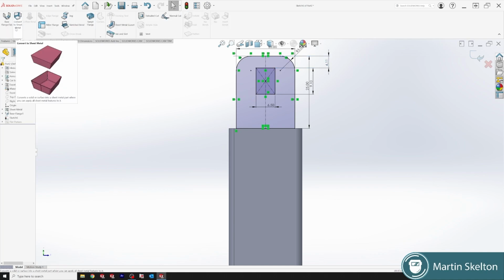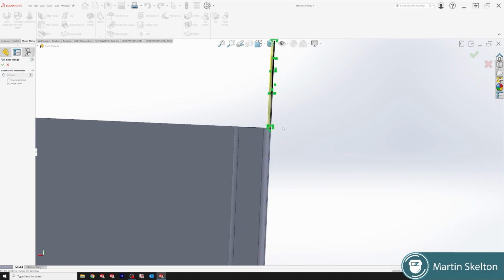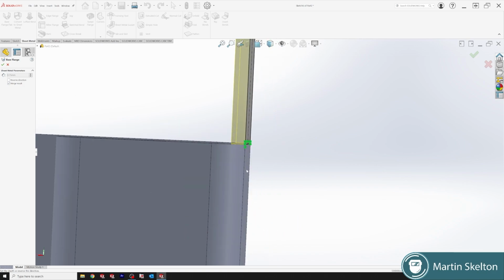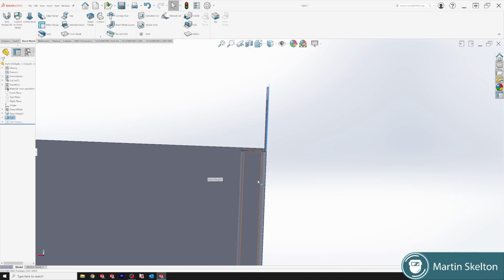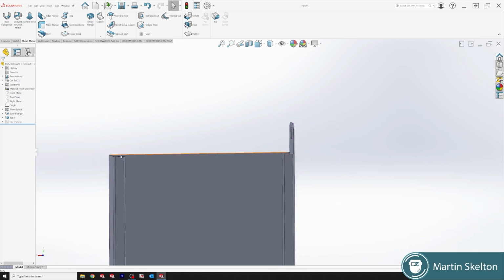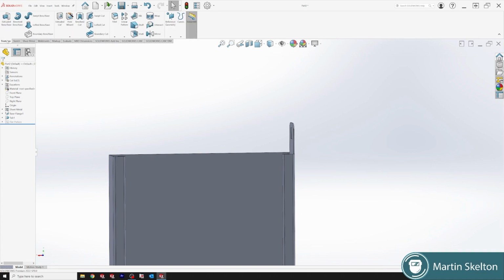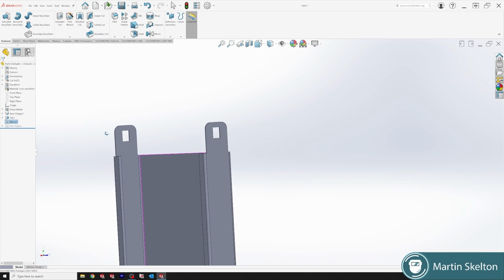Back to our sheet metal. Base flange tab. Merge result. Make sure merge result is ticked. You also check your direction because you might have the reverse direction, but since we drew it on the right side, it is perfect. And we click go. There is our tab. So we need the same tab on the opposite side. We go to features, mirror. Since we started our drawing in our center, you can now go right plane, features to mirror is tab. Close. Tab on both sides.